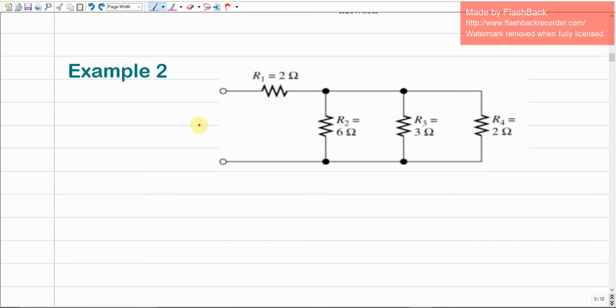So the process again starts with a simplification for this one. We have to start with the electrical current distribution. This is going to be the total current that comes from the source. If I ask you how much is the current over R1, it should be the total current, and then this total current is going to keep going. At node 1 it is going to be divided into two currents as shown here. One current is going to be I1, and the second one, let us assume, is I2. As we discussed before many times, there is no restriction or constraint on which one should be I1 and which one should be I2. It doesn't matter. I can give this I2, this I1, it doesn't matter.